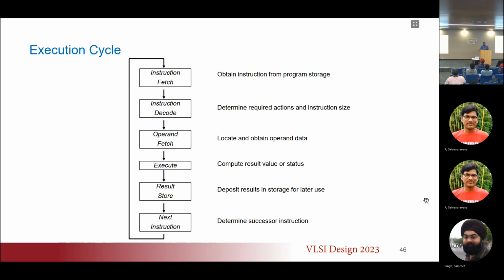So I'm fetching two instructions. Once I produce the result, I have to store it back. So I have another instruction to store the result back in many of these architectures. So I end up doing 3 instruction operations and then data operations. Each instruction operation, when you fetch from the memory, every memory read costs you power.